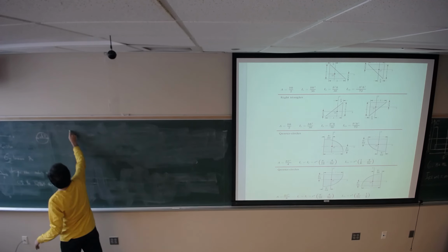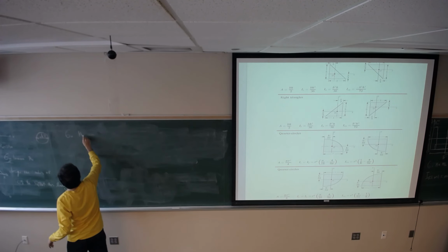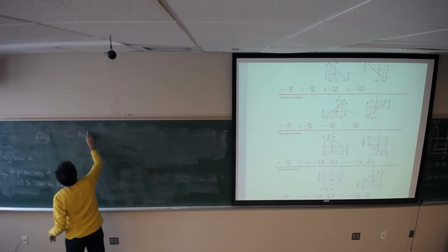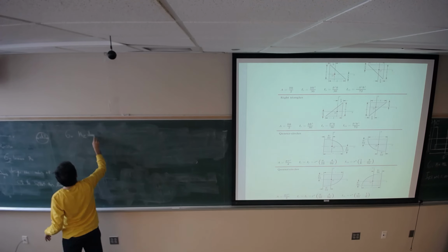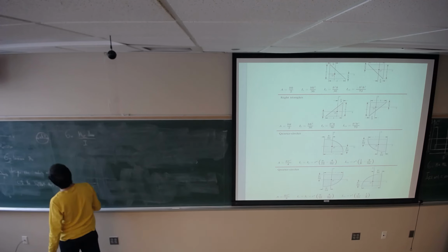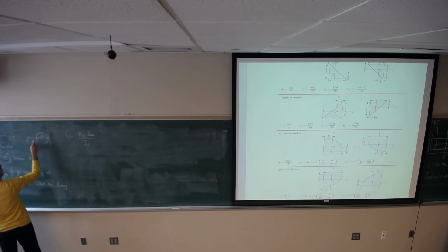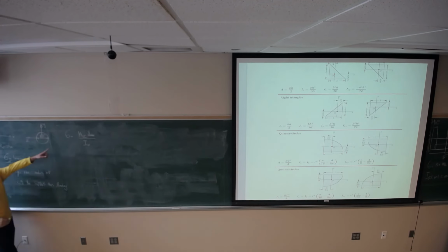So sigma is going to be Mz, the direction of the moment is about the z-axis, times Y max, or C, divided by I with respect to the z-axis. This is the z-axis, this is Y. What would be the Y max? In the circular cross section, Y max is on the top, equal to half of the diameter.